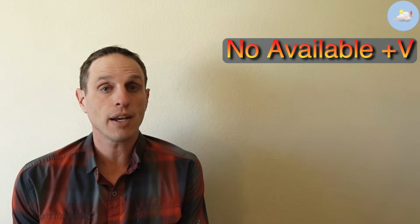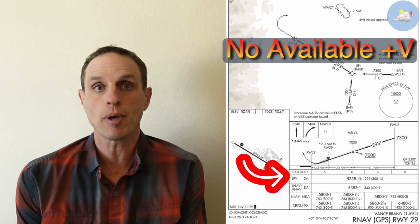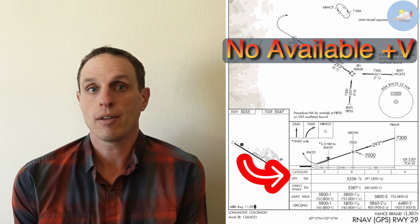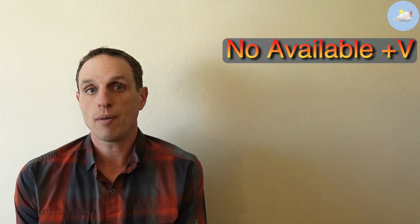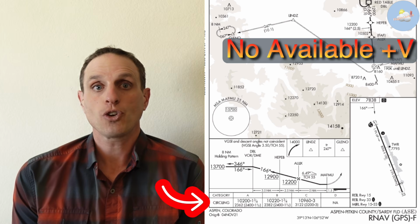Other circumstances where you will not have the +V guidance is if the approach you're using already has LPV minimums, then you already have as good as it gets. There's no reason to not use that. If LPV is available, that's what you're going to get. The other instance that you're not going to have +V is if your approach plate is circling only.